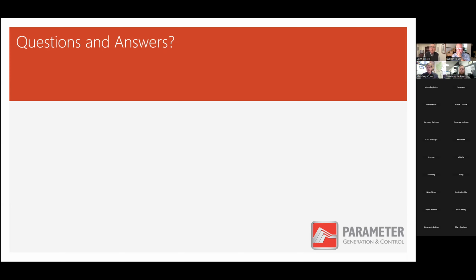Just an opinion. Yes, when we apply industrial dehumidifiers to environmental control rooms, they utilize desiccant, but also a heater to heat that desiccant to increase its ability to dehumidify, because you're basically going below, in a freezer, the frost point, and you're getting down to very low grams of water in the kilograms of air.